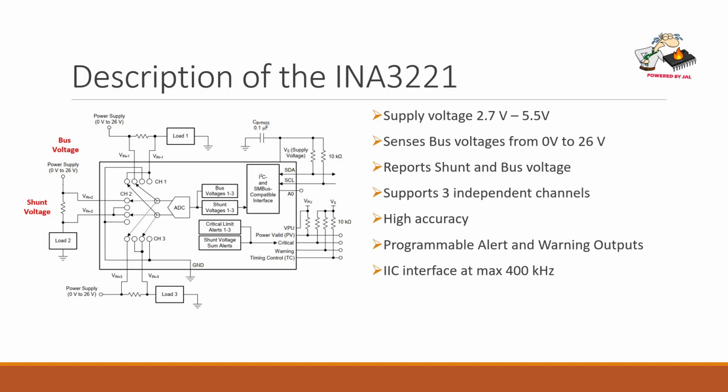And it communicates via an I2C interface at a maximum clock frequency of 400 kHz. And you can change the I2C address by changing the assignment of pin A0. You can connect it to ground, or connect it to the supply voltage, or to one of the I2C lines.